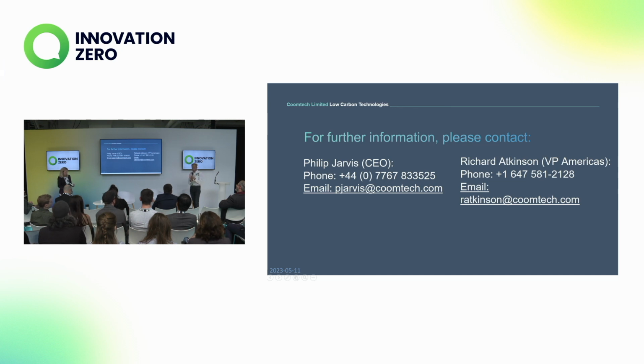The maybe not part of the answer is that we dry the surface moisture because of the air knife principle. And if you have moisture deep down inside fissures in the material, we will probably not be able to remove that. And for some food and pharma applications, that matters a lot, and others it doesn't matter at all. So, for example, I was speaking to somebody a little while ago who was trying to dry the outside of oat husks in order to remove the husk, but he didn't want to dehydrate the oats inside. So the answer to your question is yes, with some caveats.